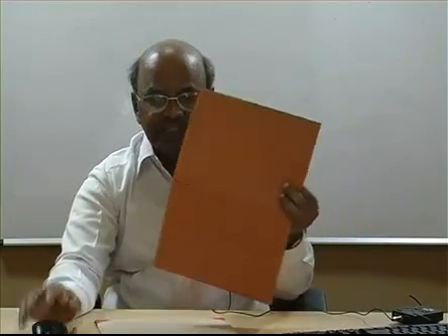So first these figures will tell you how to rotate the plane, and ultimately the horizontal plane comes and coincides with the vertical plane. But the XY line separates the two planes. Above the XY line represents the vertical plane, below the XY line represents the horizontal plane. So this is very important to remember. Let us see, take an object.